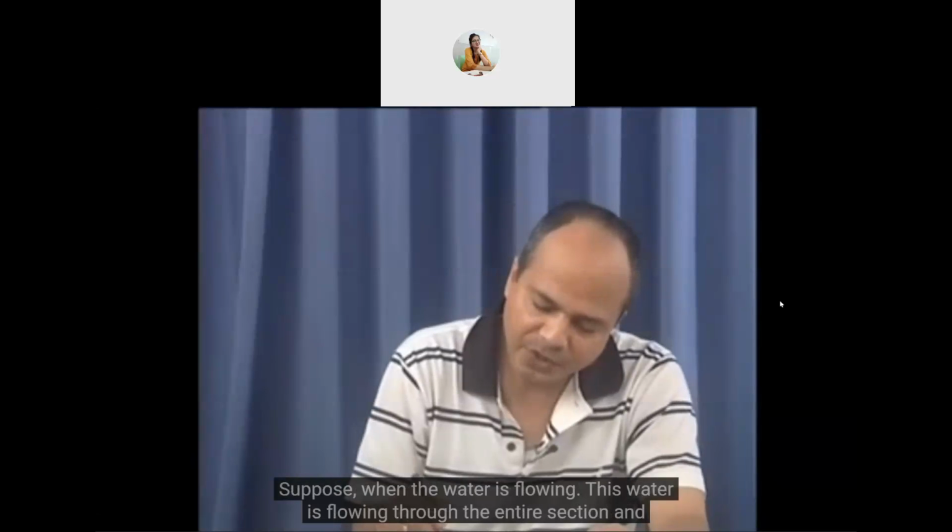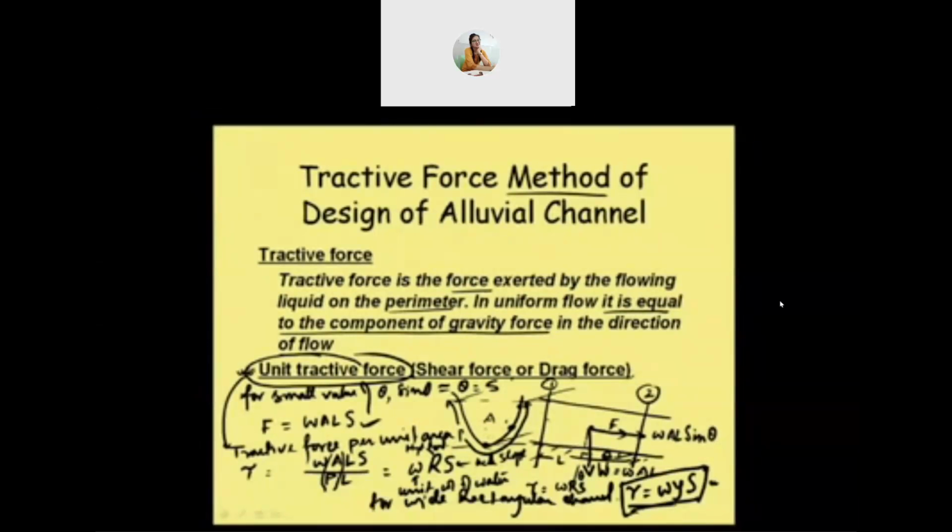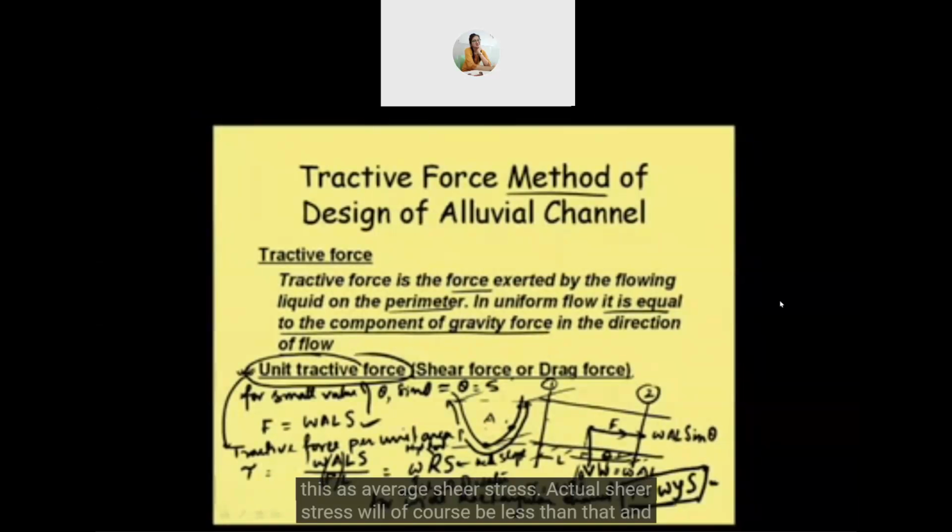Suppose water is flowing through the intersection. It is well understood that the shear stress exerted at this point and maybe at this point will not be equal. That will definitely be different. But this value we are getting by dividing the total shear force by the entire surface length, and that's why we are considering this as average shear stress. The actual shear stress will of course be a little less than that and will have some variation.